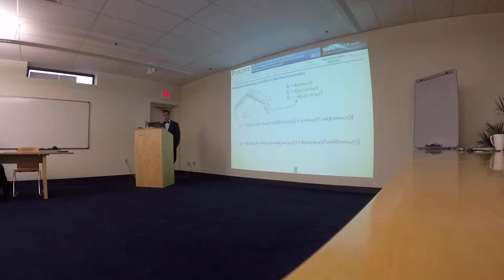And this was really interesting because from these two equations we can see how the oscillation of the payload is reflected to the pressure in a frequency way. So the x acceleration contains 1 and 3 times the frequency of the oscillation of the payload, while the y-axis contains 0, 2, and 4 times the payload oscillation.